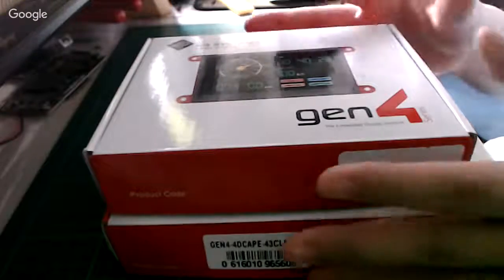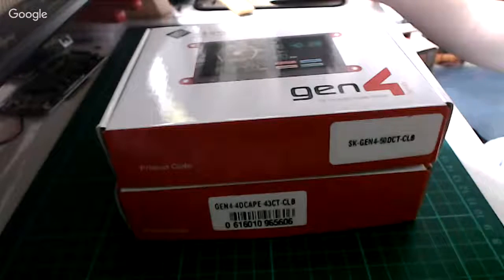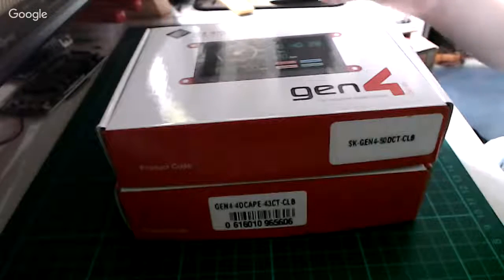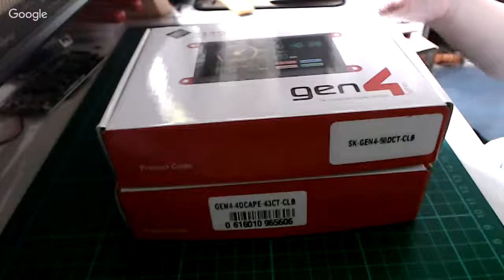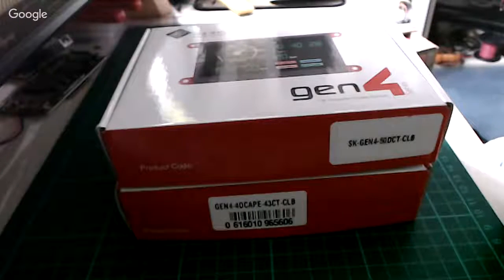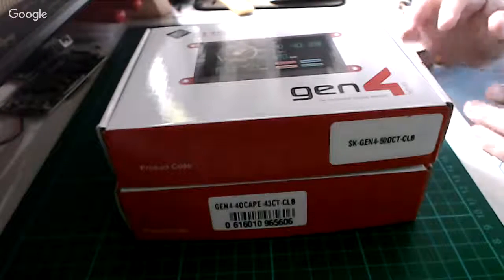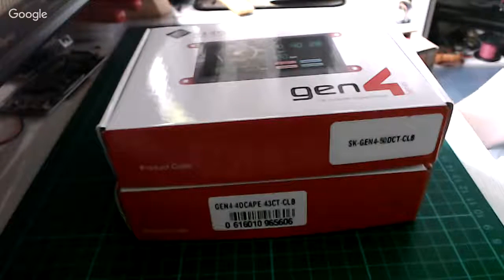Okay, so basically, Gen4 smart displays come in a few types. There is the non-touch display, which is just a normal display. They have the resistive touch as well as the capacitive touch. So what's the difference between resistive touch and capacitive touch displays? Resistive touch displays require you to apply pressure to interact with your fingers. So you cannot do things like swiping, the things that you normally do on your smartphone.